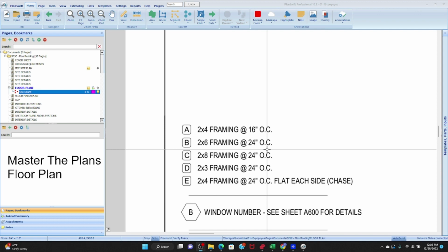Because we know how often we place them, either 16 inches or 24 inches. And so if we know how many inches in total of wall we have, and we can easily do that by converting the feet into inches, right? By multiplying by 12, because for every 1 foot we have 12 inches. And so that's a little easy construction math that we always have to be able to do off the top of our head,